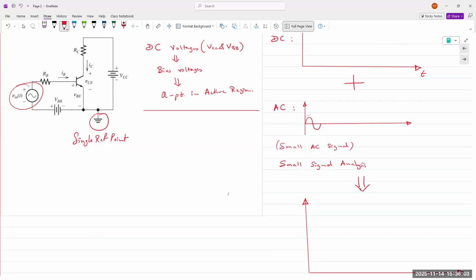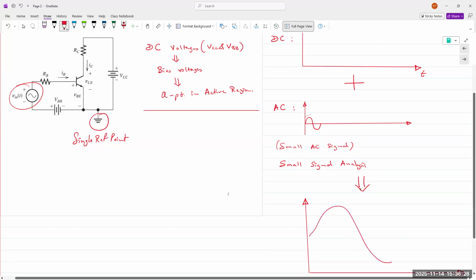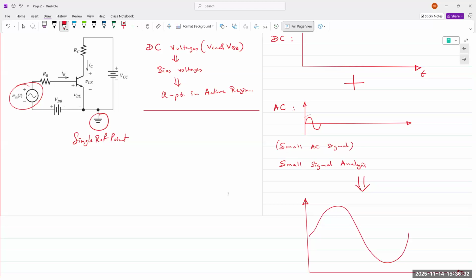In this transistor amplifier, the output DC bias is VCC, so it would represent just VCC. The common emitter voltage divider bias that we used had a single VCC, so only a single supply, and it didn't actually matter. Anyway, the point still remains that we get an amplified version, or a replica, of that input signal.